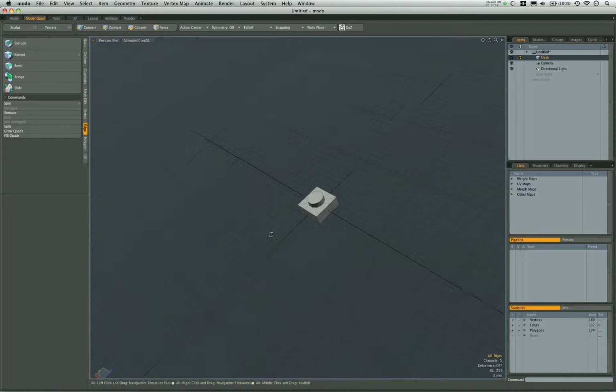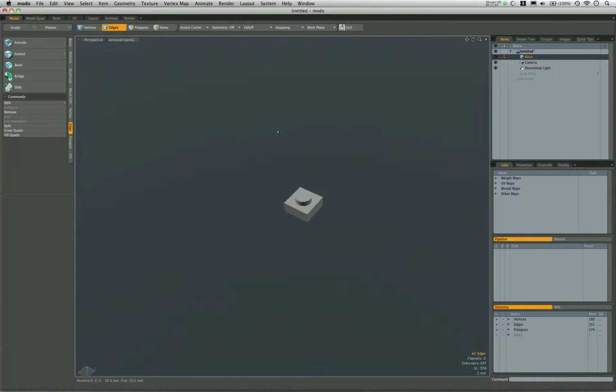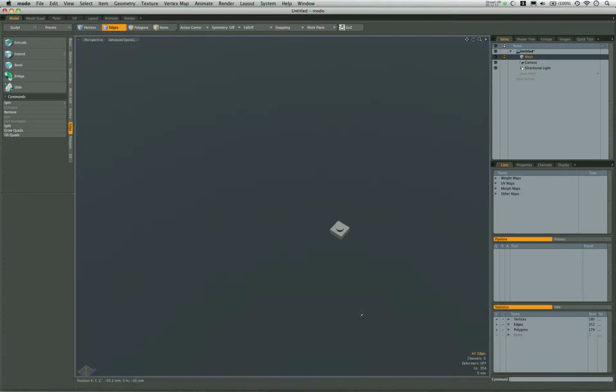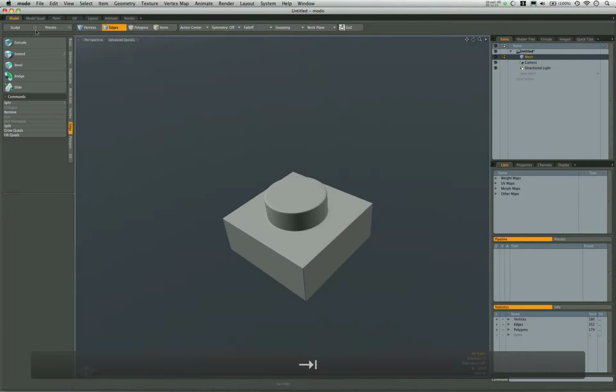You get much smaller than that, and you really have a hard time telling the difference, especially if we quickly turn off, let's go to model single here, so that I have my wireframes off. The difference becomes much less noticeable, especially when we'll add anti-aliasing on a finished render. You're really not going to notice too much of a difference there. And you can see it drops to 356 polygons from 5600 if you're here at full subdivision.